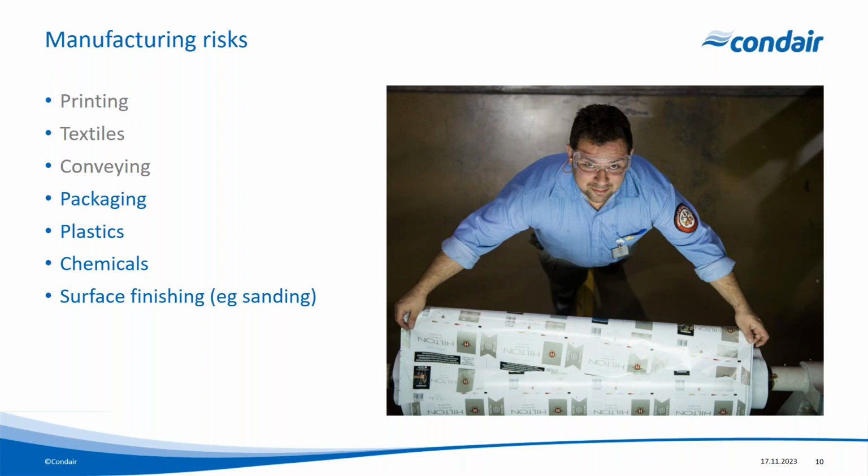Surface finishing, again, if you've got fibers that are coming off the sanding deck and are negatively charged and the sanding deck is positively charged, that dust will be attracted back onto the surface, so it will affect the finishing and reduce the quality of the material.